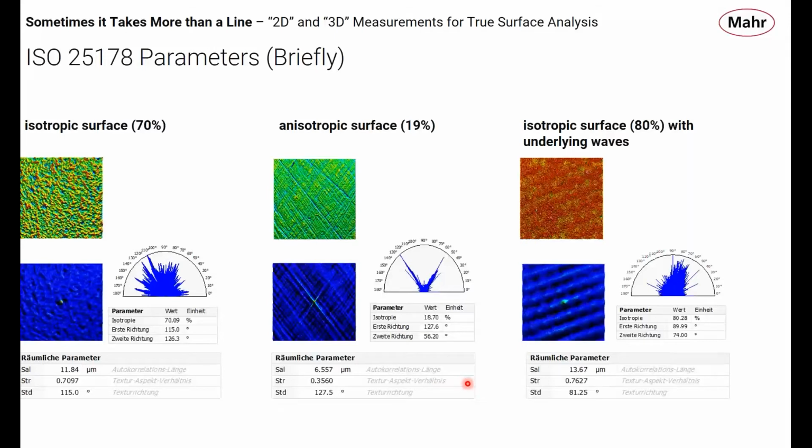If that were 1, it means that there is no aspect to the texture. It's even in all directions. Not necessarily isotropic, but the texture directions we find are even. But here it says no, actually. Indeed, those northwest to southeast honing marks are actually a stronger signal than the southwest to northeast.